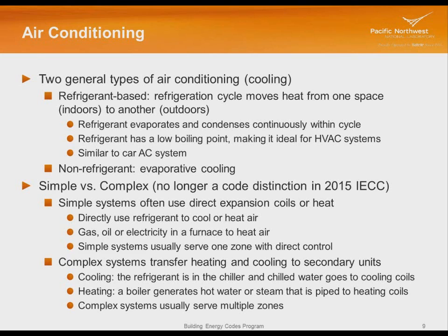And refrigerant has a low boiling point. In other words, we use it just like you boil water on a stove, except that boiling is occurring down at 25 or 30 degrees. So as it boils, it will suck heat out of the air, and that makes it ideal for an HVAC system. And that refrigerant is all contained within a pressurized system.